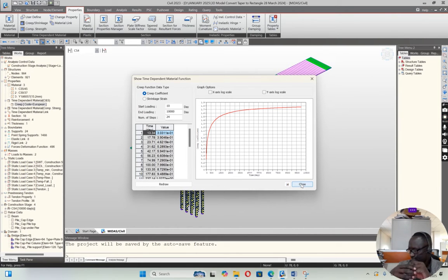If I give you a reinforced concrete and post tension concrete, and I use grade 25, grade 25 is good for capacity, for reinforcement. But if you subject that grade 25 to tensioning forces, and you know these forces are in 1860 MPa, which comes to about maybe 1395 MPa if you use 0.75 jacking force, taking care of all these other losses and the rest, then definitely you'll find that this concrete will fail by crushing.